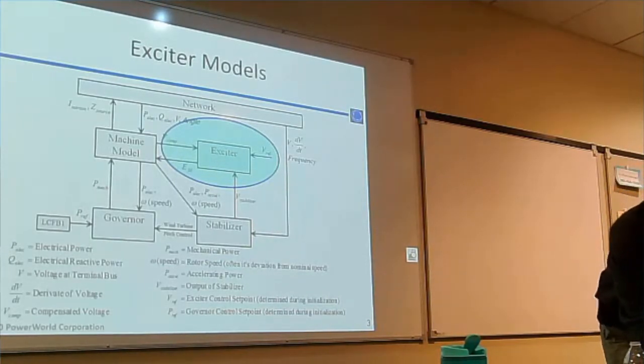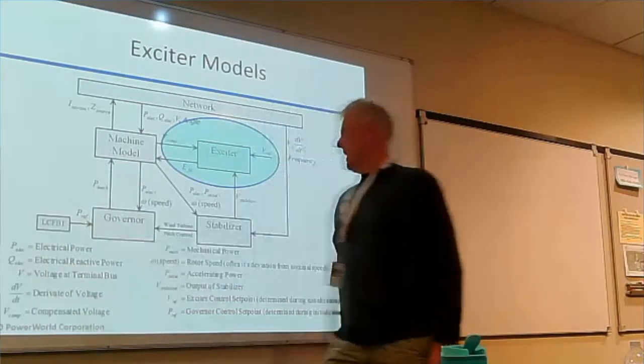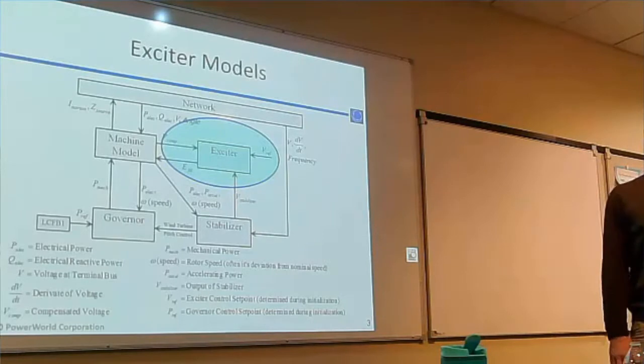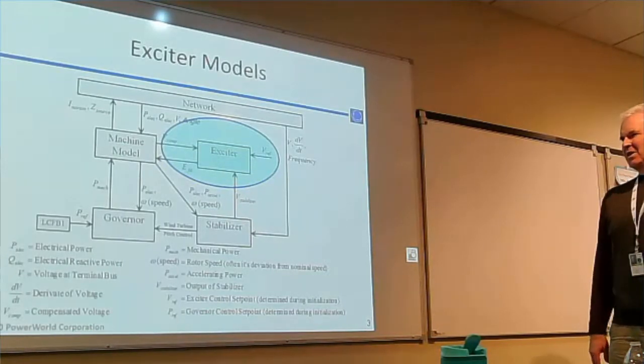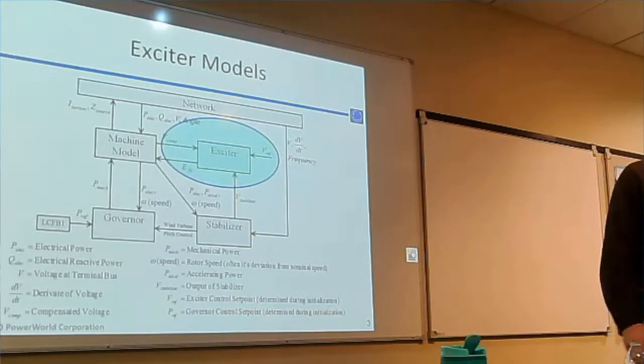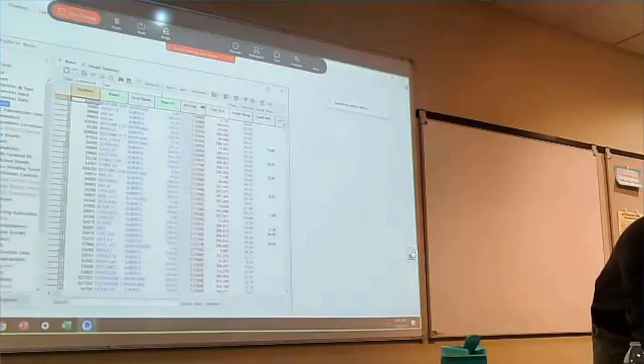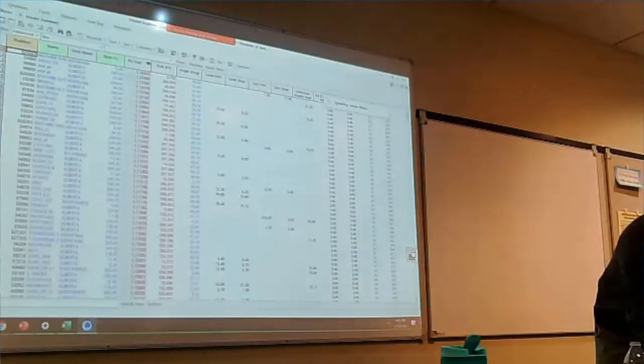What's the LCFB? That's a model that can change the set point on the governor. We're not going to really talk about that today. That would be in the longer presentation. It stands for load control frequency bias. Okay. Just looking at the system frequency and maybe changing it.